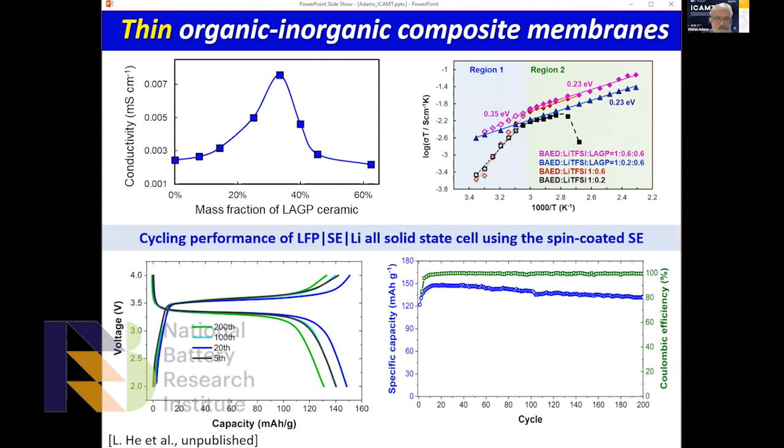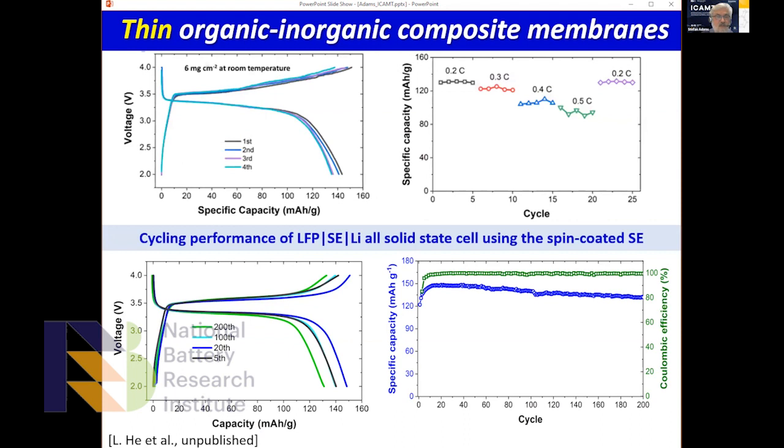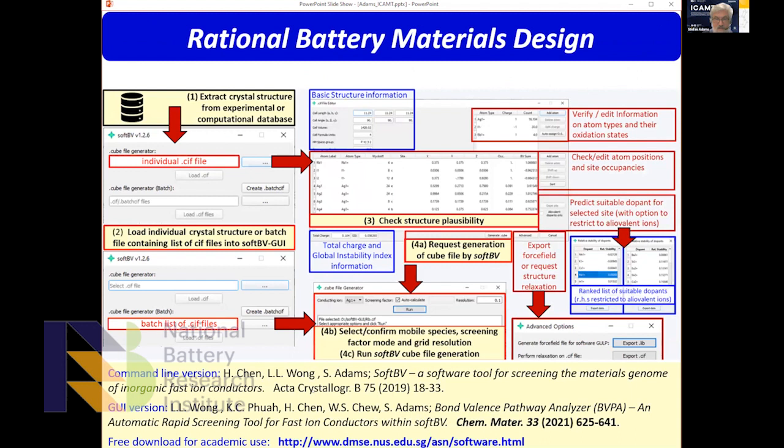So we can use the LFP batteries, rather stable for such solid electrolyte batteries. We can also get to relatively high loading, which is very important. You can always get nice performance in the batteries if you use very little cathode material only, but for practical use you need rather thick cathode layers, and then we need to optimize the transport of the ions and of the electrons in this cathode layer.